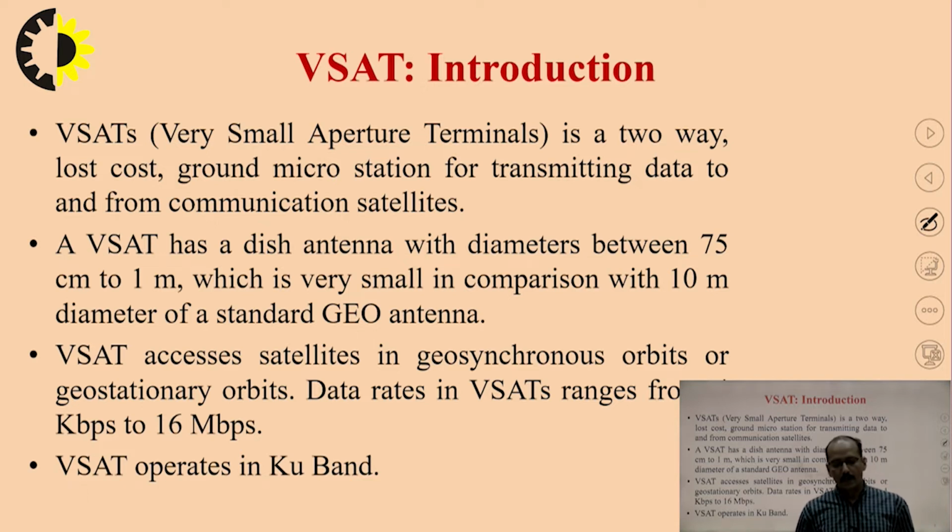As you are talking about that cable operator or cable services, in today's scenario they are using the direct to home TV system. In that system, you are just creating a small earth station at your home and getting the data from the satellite directly. So in that complete picture, the main thing is the very small aperture terminal, or we can say a small micro earth station that is going to be created at a location. So VSAT came into being from that perspective.